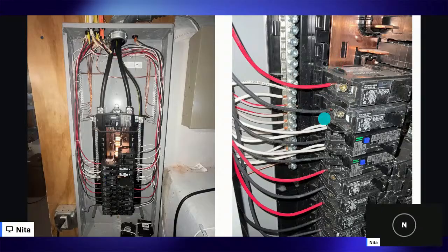In your book, they call them OPDs, or overcurrent protection devices. We call them circuit breakers. I haven't explained those in detail just yet. So the only place you will see green or copper is on the grounding bus bar, which in this picture is on the left-hand side. Actually, I'm not going to say the only place, but if you are looking for grounding wires, they will terminate on your grounding bus bar. A grounding wire can be a bare copper wire, or it can be insulated with green sheathing.